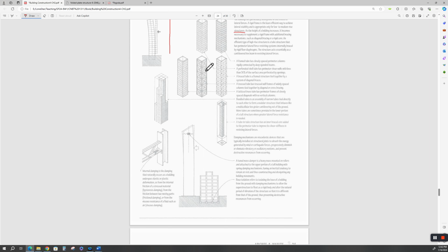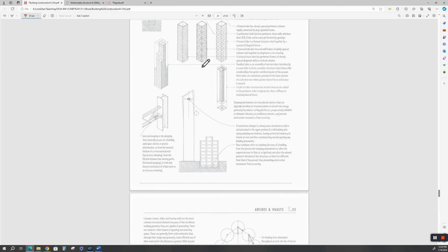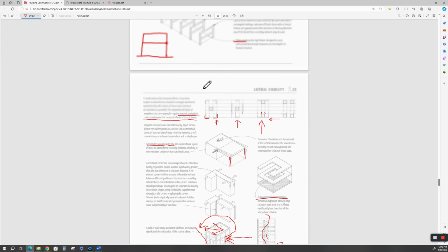Because I guarantee you, every one of these is going to have a central elevator core that runs all the way down through here, where your MEP, your mechanical, electrical, and plumbing, and your elevators go, and that will be a heavy reinforced concrete tube, and it will be used as your center column shear tube. And then your stairwells. Where are you going to put your stairwells? You're going to put them fire exit stairs. You can't use the elevator.